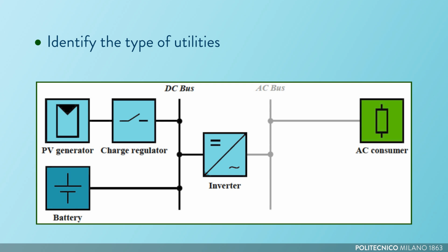If it is going to be powered in alternating current, it will be necessary to insert a DC-AC converter interface. This device must be sized to be able to sustain the required power and to be supplied by the DC voltage level of the battery and the system. All these aspects impose constraints on the system size, and you may need to retrace your steps to be sure that everything is compatible and appropriately selected.